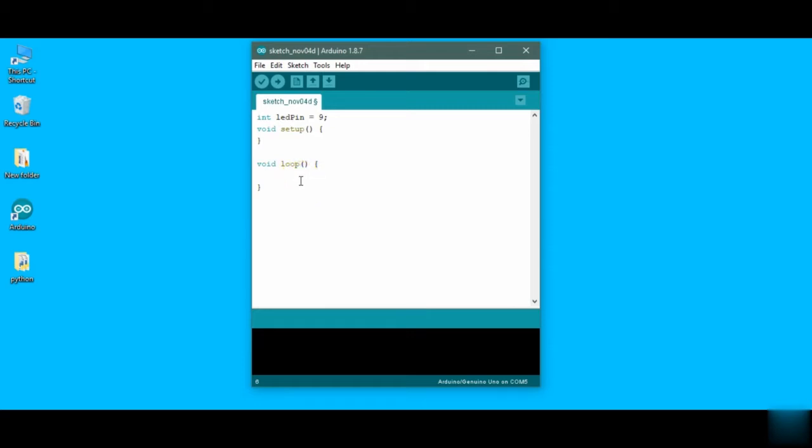And now in the for loop we use a variable called fade and initially provide it 0, and after that the condition is fade less than or equal to 255, which is a particular value for LED brightness, and this is the maximum that we use here. After that the LED will burn out. And after this we have fade incremented by 5. This is a common example. You can also find it in your example sample codes, and I will show you in a moment.